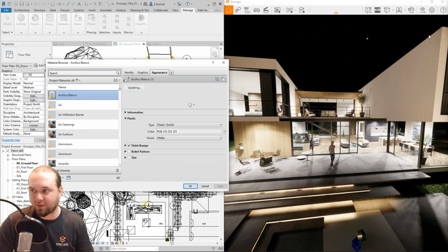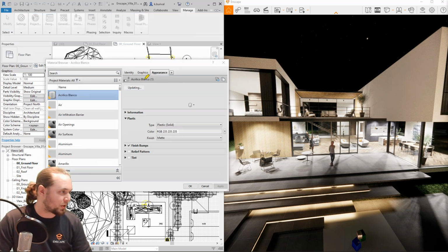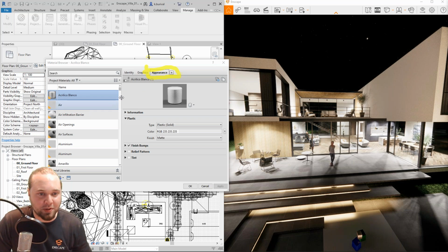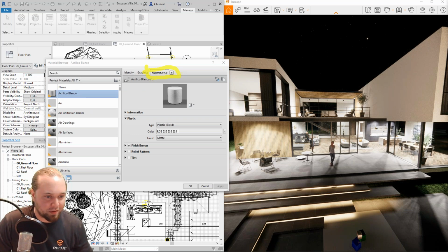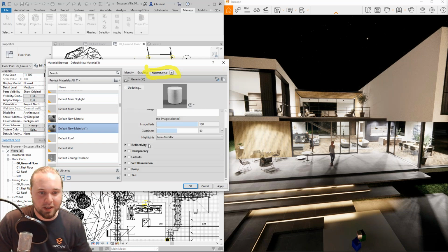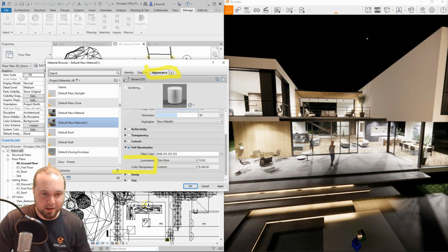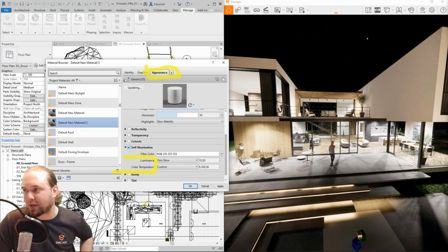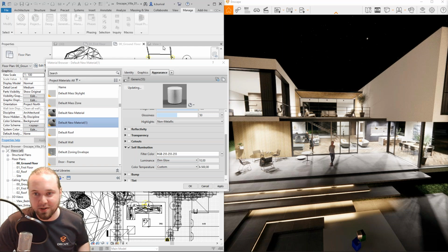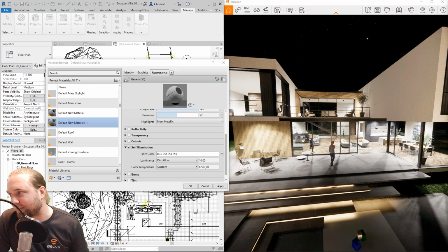So you have your appearance library. This is where Enscape draws all its material information from. And if you see those light blotches, light noise, you have a material somewhere in your scene where self-illumination is enabled, and that's probably pretty bright and pretty small. That is where these things come from. So yeah, look out for that. If you can find a solution, get in contact with us, and we'd be happy to help you.